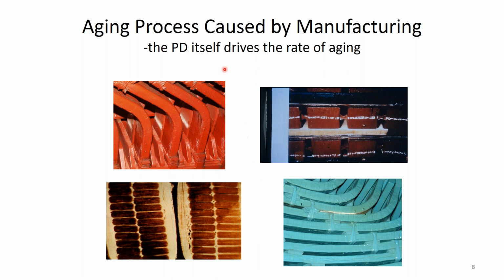Okay, these are photographs from 4 different machines where there were manufacturing problems. It gives rise to PD because PD includes electrons and ions that bombard the epoxy insulation. Eventually, it'll cut a hole through that insulation. You'll get a process called electric treeing or electric tracking.